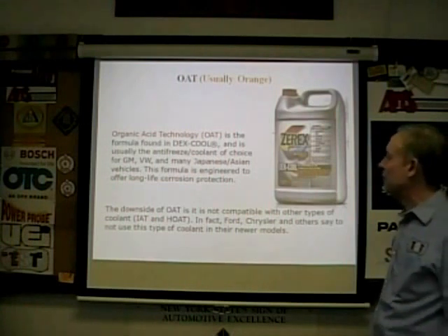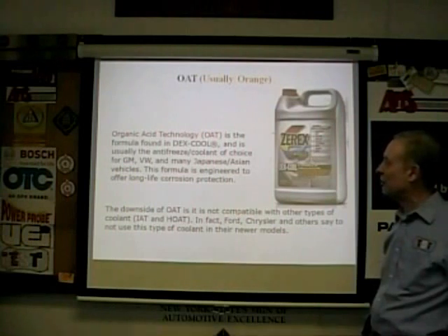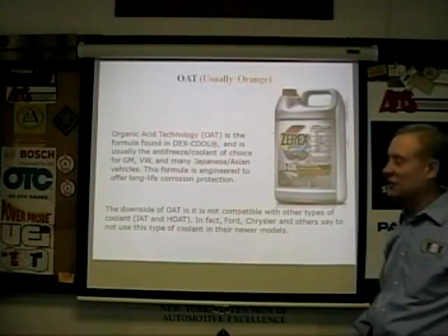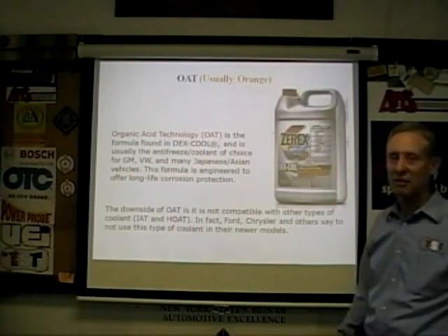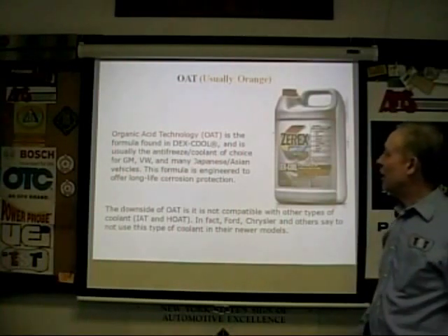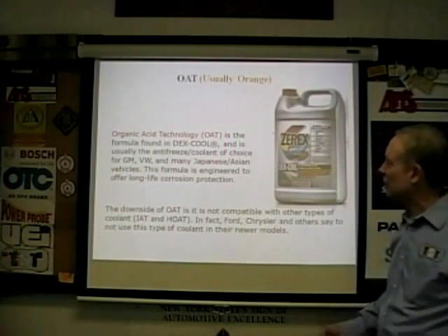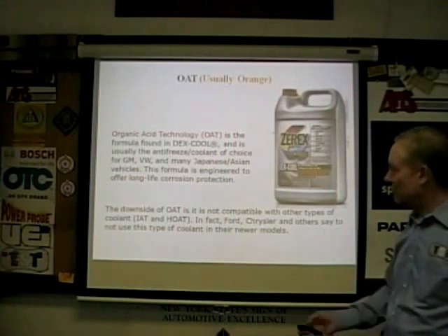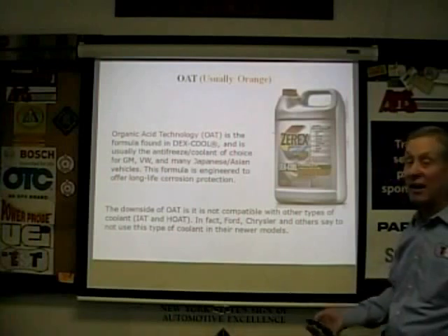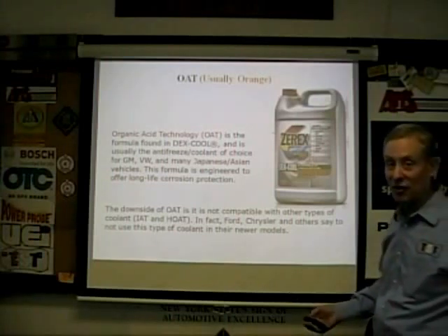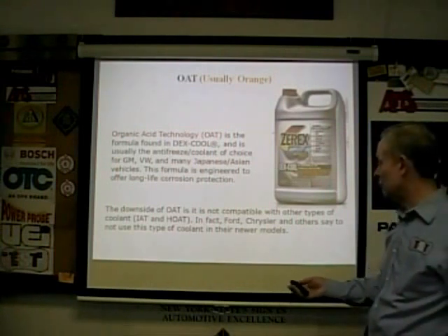Dexcool's just one brand. And you can see there's all these different places, parts of the world where OAT technology is being used. It's, I guess, probably the predominant type of coolant now until we get into hybrids and so forth. GM, VW, Japanese, Americans, a lot of vehicles are using OAT technology. It's good for long life. I don't know that I would totally follow the spec on how long the life is. I'm still a big believer in flushing coolant every 2 or 3 years and making sure you use distilled water.